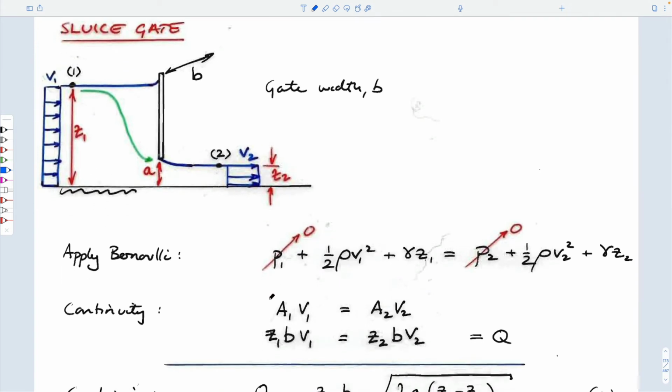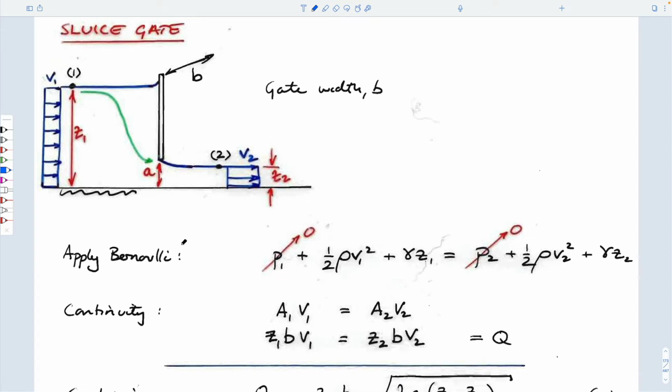So, same idea if we want to be able to measure flows in the field. As I say, it wouldn't be an unusual thing for some of you in your majors, an environmental systems engineer or mining engineer, to go out on site and measure flow within a small stream. You take a board with you that has either a V notch in it or a rectangular notch. This one is actually an undershot, so you turn it upside down so it flows under. Usually you have it as overshot, so it's a V in the top of the board that you put on the stream. I should probably show a picture, but I don't have one really at hand.